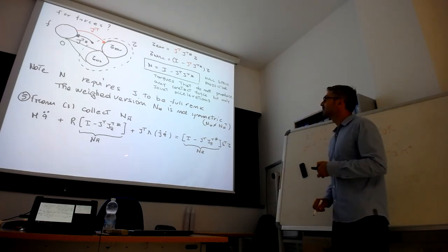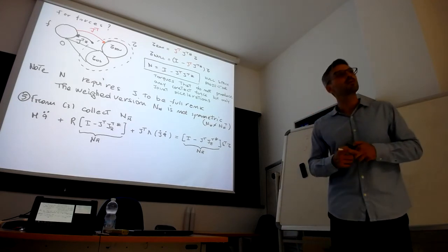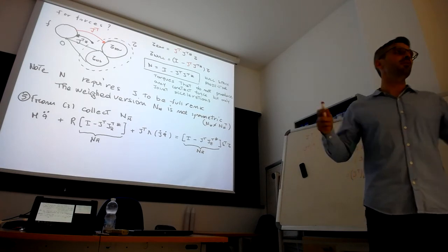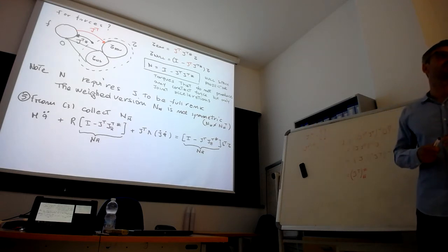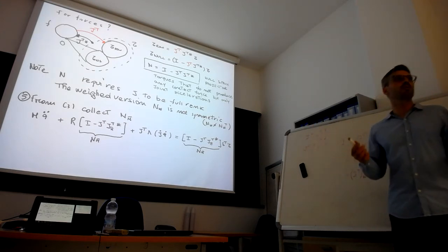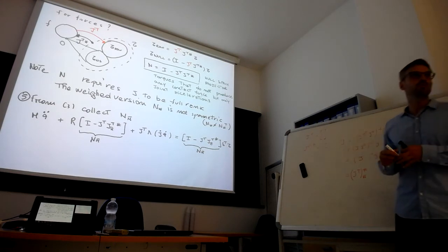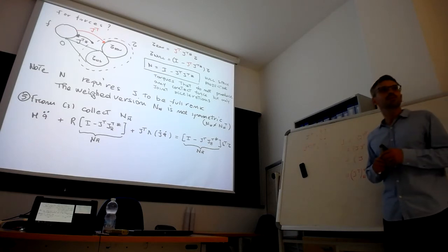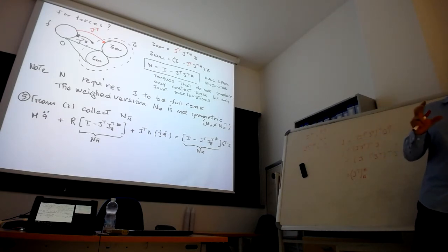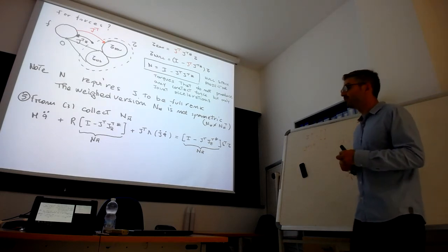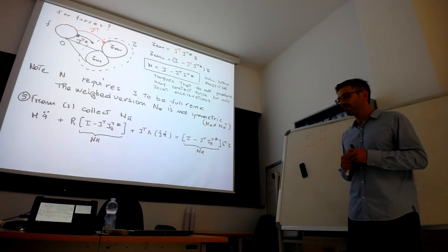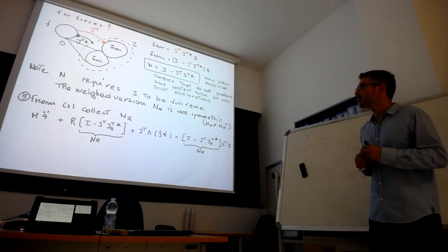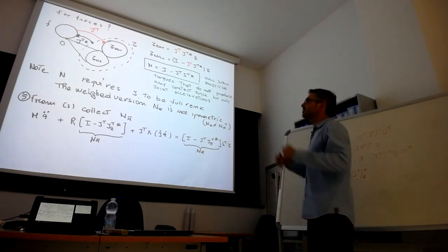Does it work if the J matrix is a fat matrix instead of a skinny matrix because of the degrees of freedom of the robot? Yeah, normally the task is smaller than the number of degrees of freedom of the robot, but it could be the other way around. In that case, you need to do the proper computation of the inverse. But yes, most of the time the Jacobian is fat, or at maximum square. In the case, for example, of a quadruped, you have the square Jacobian whenever you have all the feet on the ground, the four legs. But in the other cases, it's rectangular fat.